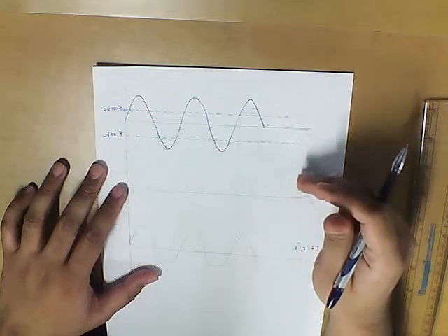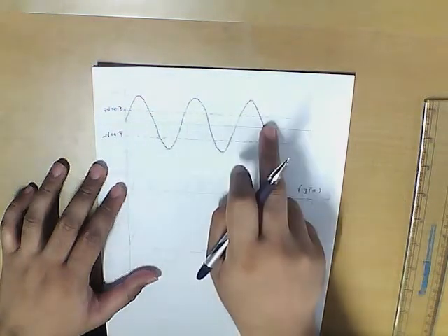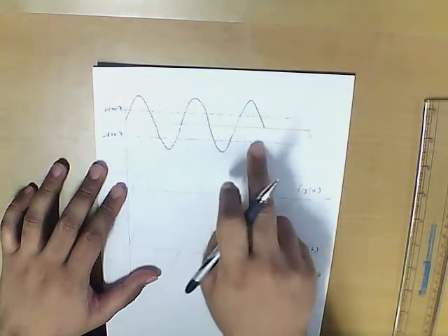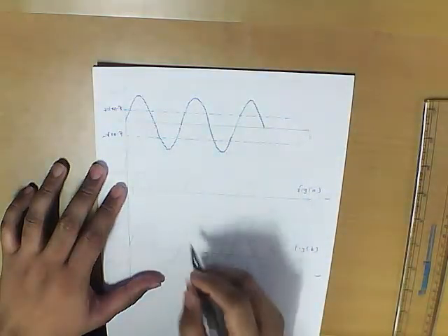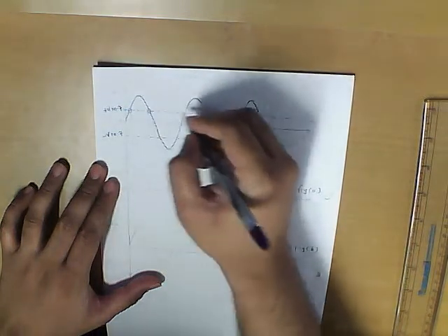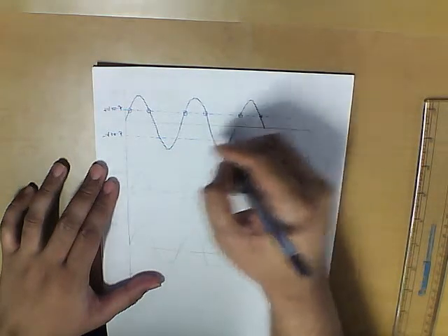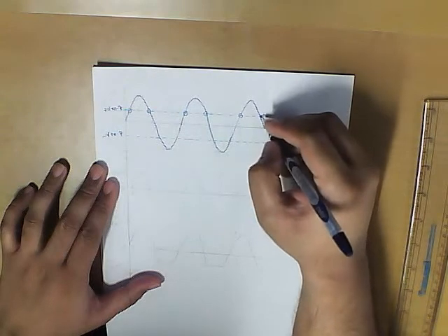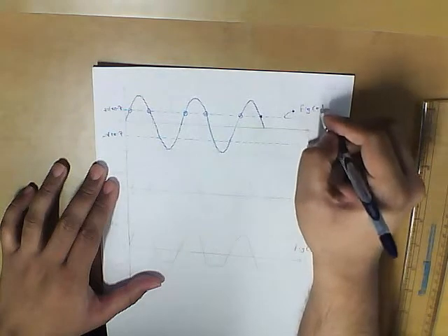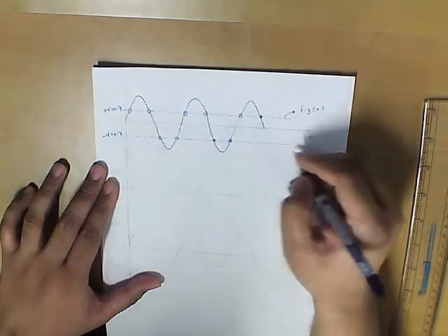It is a negative clipper. That means in figure A, everything that is below the level is going to get clipped off, and in figure B, everything below this level is going to get clipped off. That is why, for figure A, when we take these points, these are the clipping points actually, and this is the figure A level. These points we need to project in figure B.